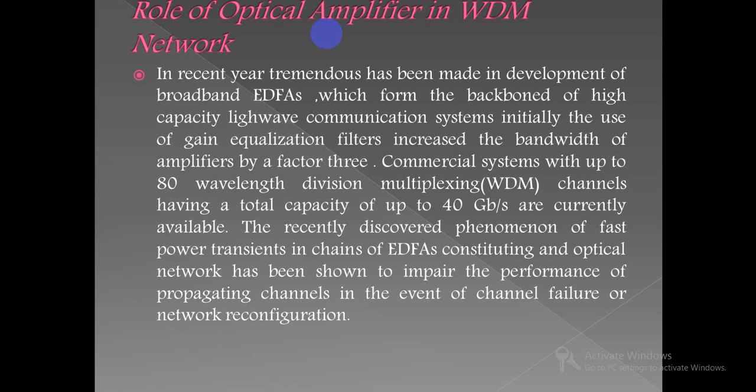In the last dozen years, tremendous progress has been made in the development of EDFA components and technology, including the erbium doped fiber, semiconductor pump lasers, passive components and splicing and assembly technology. In the research area, an EDFA with a bandwidth of 84 nanometer was recently demonstrated. Using this high performance amplifier, long distance transmission at 1 terabit per second was achieved for the first time.